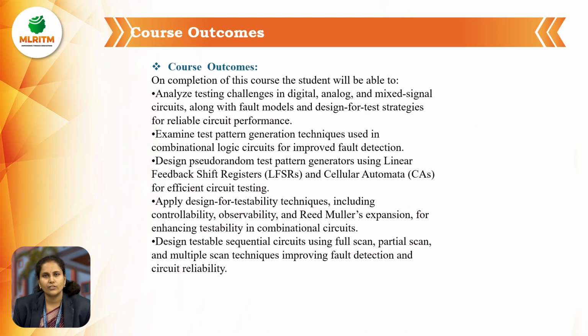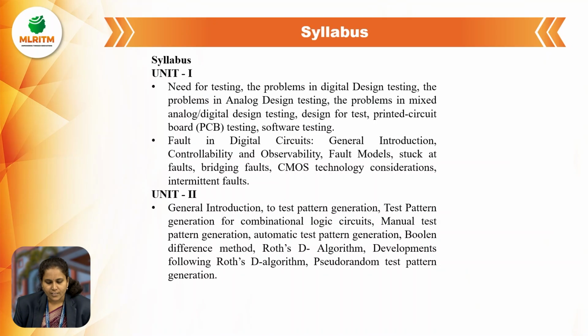For those, we are going to see different techniques, Reed-Muller's technique as well as linear feedback shift register. With linear feedback shift register, we are going to design the test pattern generations.